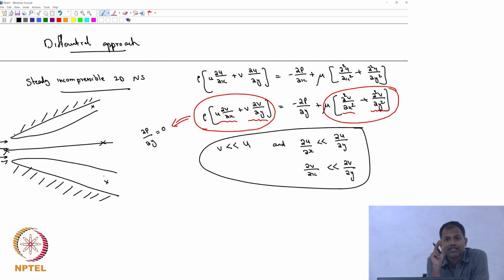So there we are basically saying that the pressure variation is only in the x direction, right? We can actually show that. If you look at the v velocity, all of them will identically go to 0, and therefore we will see that dou p by dou y is 0, and p is not a function of y. Now I know that v is not 0, so none of the terms are actually 0, but they are all small. So in other words, the flow is going to be very similar to what you will have in your pipe flow. The v component is very small.